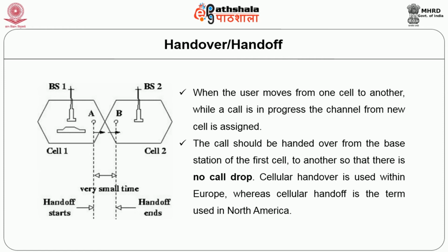What is this term? We have seen in the cellular system also that since the antennas are low power, as the user moves away from one, the strength of the signal will diminish. At the same time, the strength from the neighboring base station increases. So, the caller's service has to be moved to the new base station, and this situation is known as handover. Now, the only requirement for handover is that it should be carefully performed so that there is no call drop, and also the performance should not be degraded.